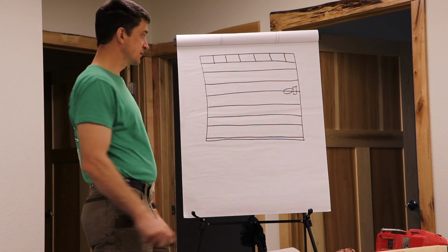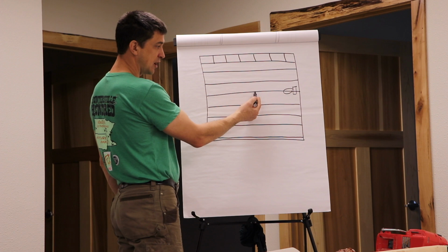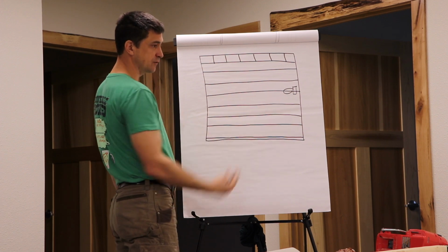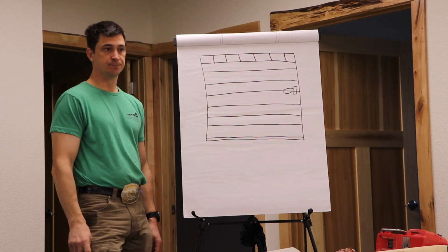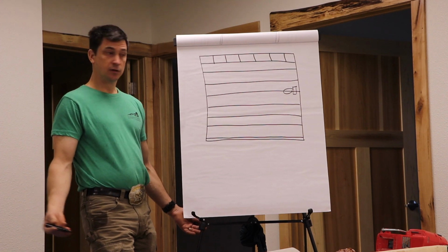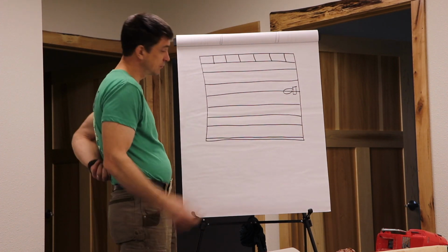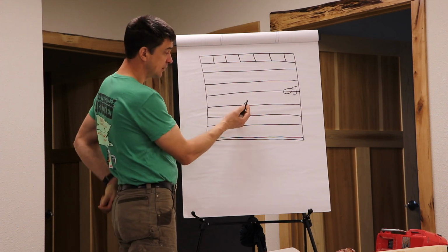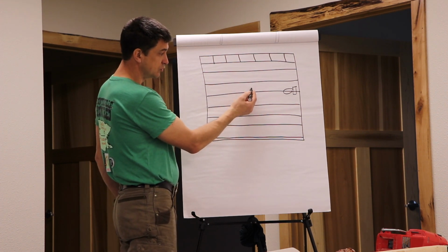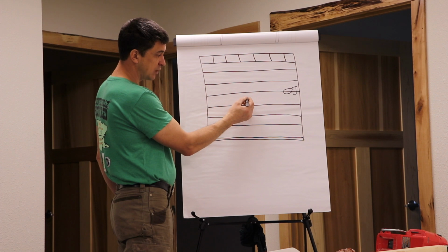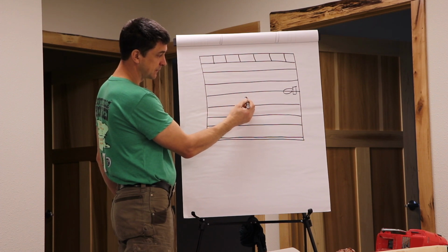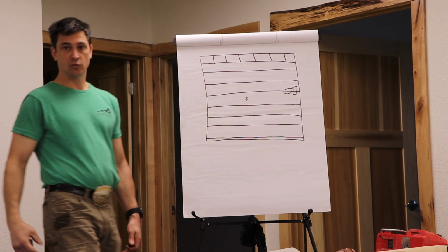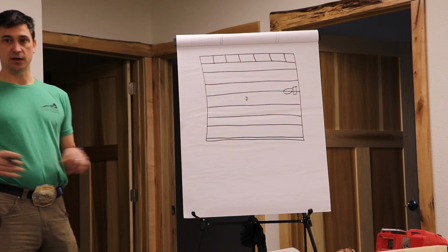Okay? So, is there a problem if I put this joist in a few inches off of the layout? Not really. Unless you're nailing down a sheeting. Maybe so. Just cut it. So we can deal with that. The other thing, like, we can move it. We just have to watch our span here that we don't exceed what our floor sheathing can handle.